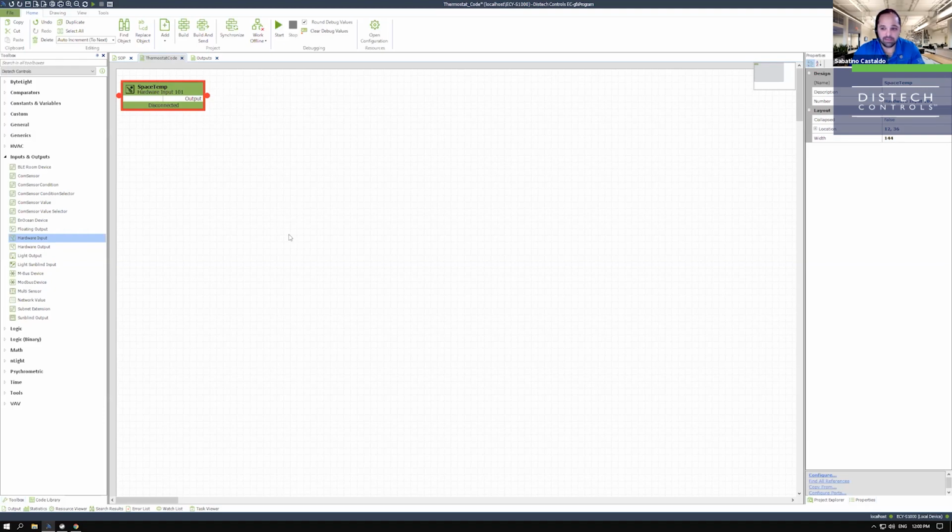So the Eclipse controllers will handle, you know, a soft limit of 2,000 objects. That'll include all BACnet objects. Now, equal blocks, logic blocks, those don't really count. They're code space, they're code writing. So it doesn't really matter for those, but the objects themselves, around 2,000 objects, that's what we say. And so this page can be as big as you like.